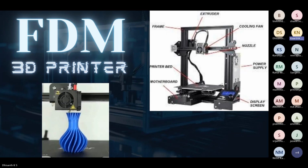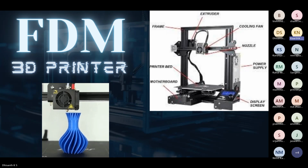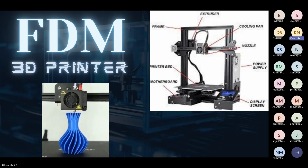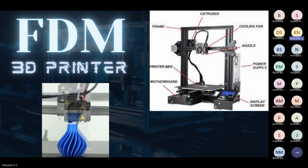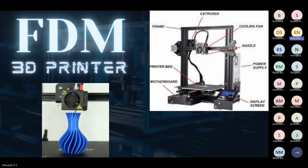Like the below image, you can see how the FDM 3D printer prints layer by layer. And on the right hand side, there are the components of an FDM 3D printer. We have the printer bed. As I said before, it should be set to a temperature for better adhesion. And we have to make sure the print bed is laid flat, not tilted.